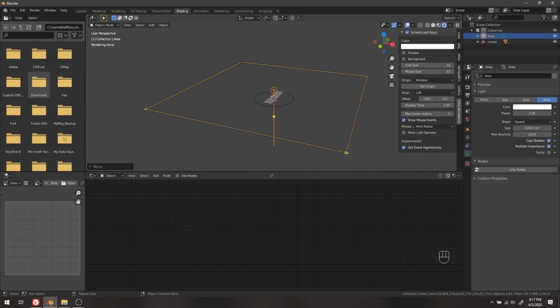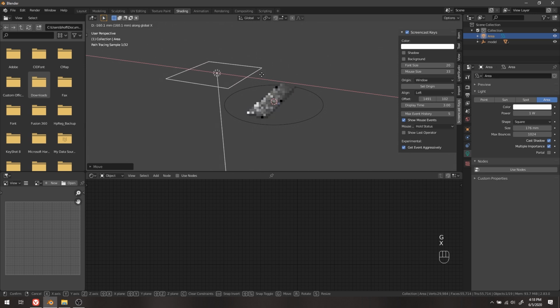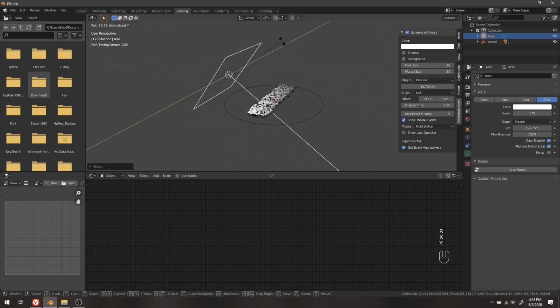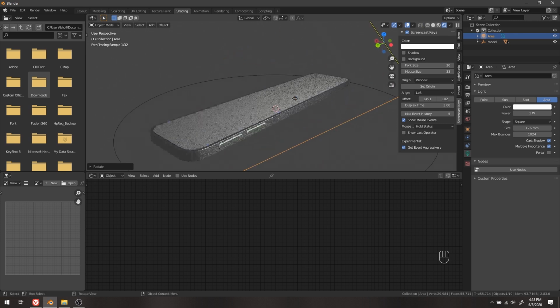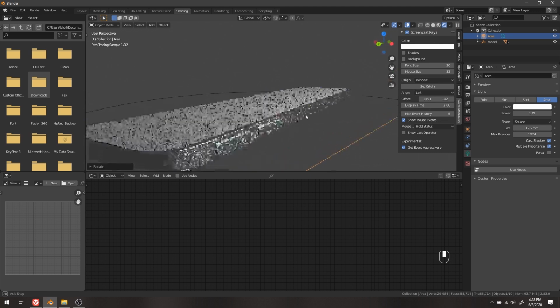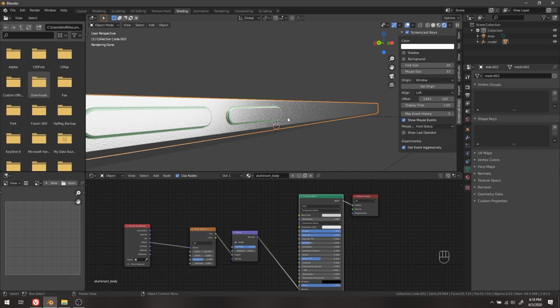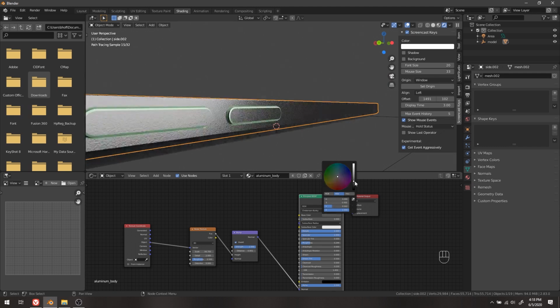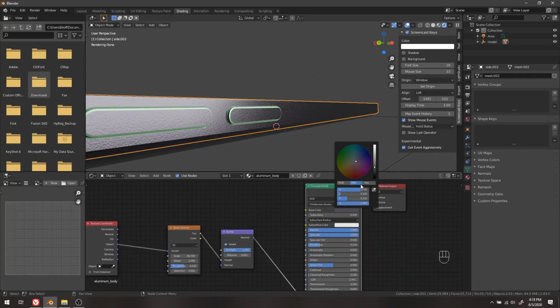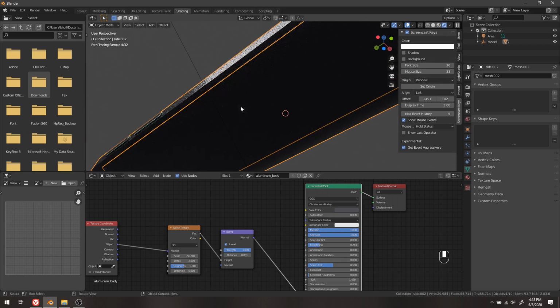Don't ask me why. You can go manipulate all of this in the viewport by clicking on the border of the light. And then I'm just going to use the grab command next to move it off to the side, R to rotate it, and we get a little bit of idea of exactly what we're looking at. Now we'll get more in depth with the lighting after we finish the materials, but that's looking pretty nice. Maybe we select that again, make it more of a space gray, bring it down a bit, put a little blue purple in it, just a hair. That's a little bit too much. I like having my color selection be hue, saturation, and value because it's easy to change how saturated and how dark the material is. We're going to run with that for right now.